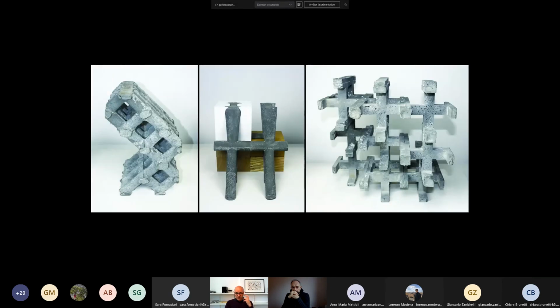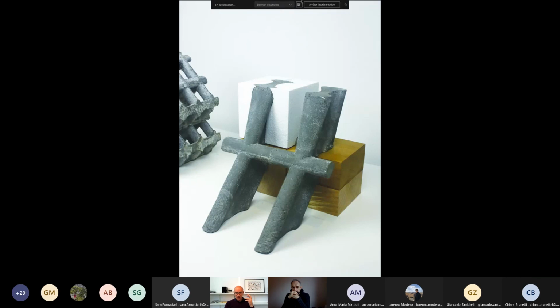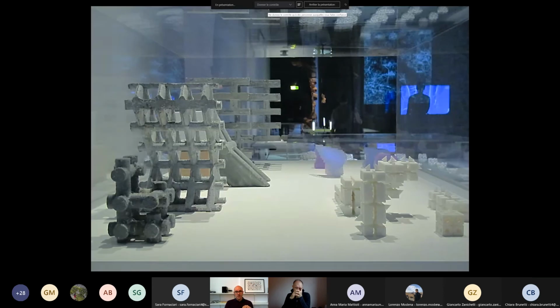And by the way, the very idea when I worked on this U-cube stuff was to have those cubes made of insulating material, so that the concrete and the structural component are never in contact, neither with the inside nor with the outside. So you don't have the kind of thermal bridges you can have in construction. Then you solve this issue of thermal bridges once and for all.